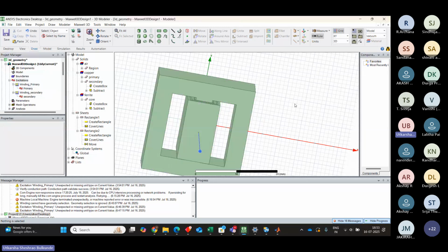It will not give you the same result as the wound, but for analysis, why do people consider it as one conductor only? Because if I specify 100 conductors, it will take a lot of time to simulate. So while teaching, it is easy for me to specify it as one conductor so that I can tell you the analysis part easily, right? So now it is like for one turn, understood?